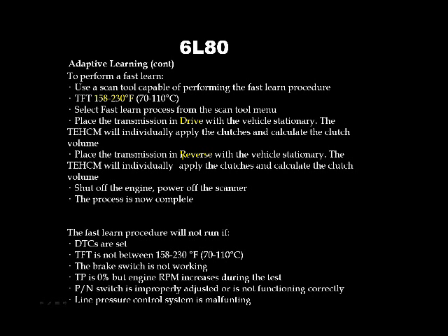When you're done with it, it will tell you that the process is complete. You shut the engine off, unpower your scanner, and you've done the fast learn. You're ready for your road test.